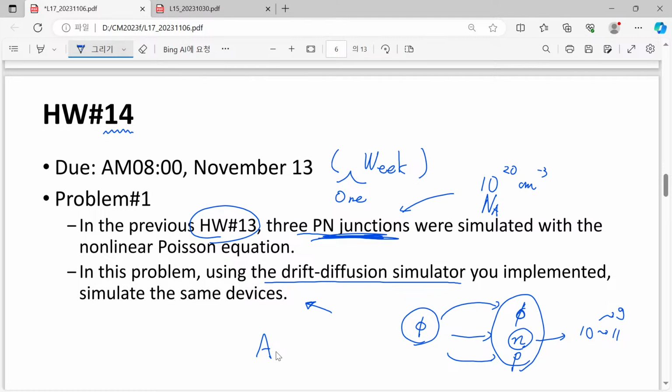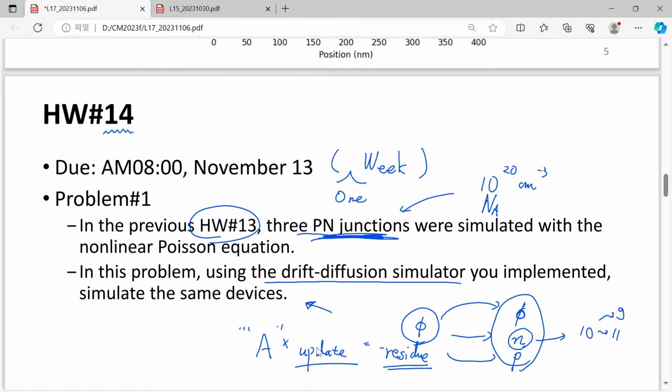Then your update vector is also completely wrong, because your update vector is simply given by this equation, and when you have a wrong matrix, then although your residual function is correct, your update will be directed in a wrong direction. Then yes, the solution does not converge, it will diverge.